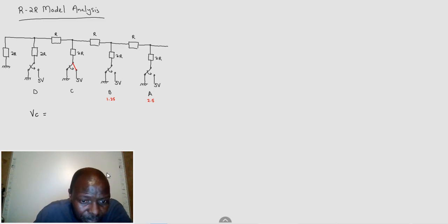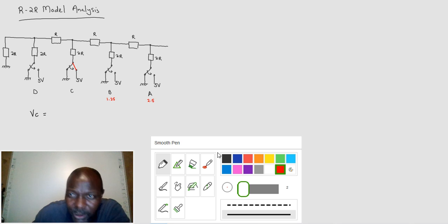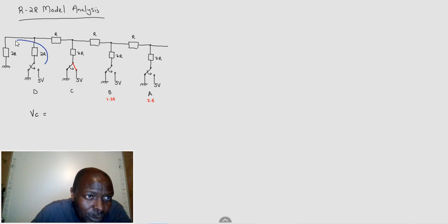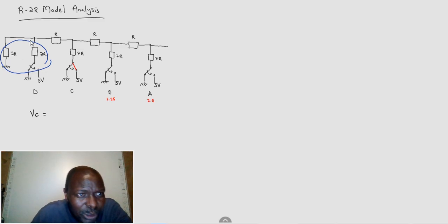These two, I'll do it right there, because doing this sketchy size does not make sense to me anymore. We know the circuit now. These two are going to resolve, because being parallel and grounded on the one side and connected together on the other side, they are parallel. So 2R times 2R over 2R plus 2R gives half of each, because they are equal. So that is R. So this one side is 2R. All right, we are done with that.